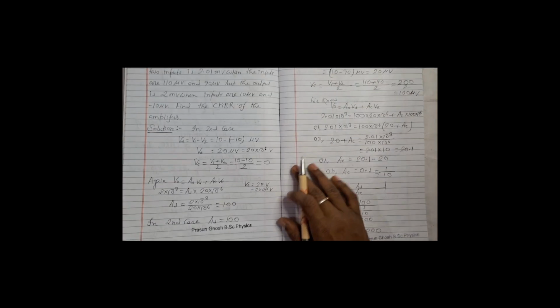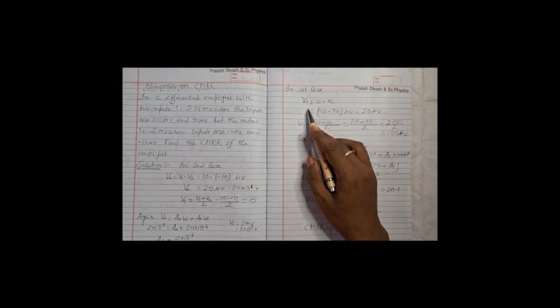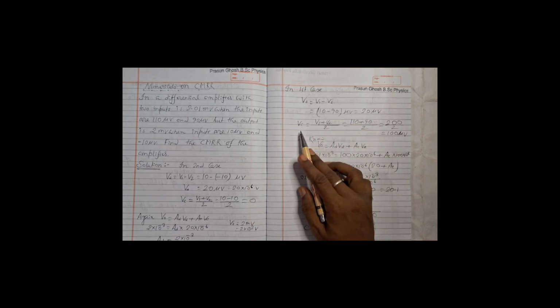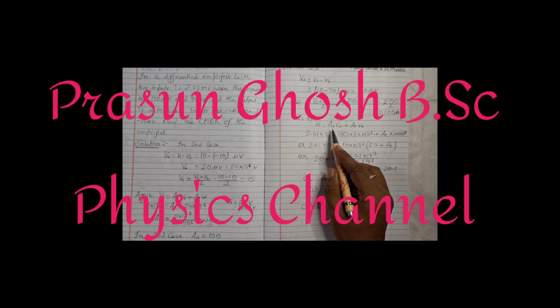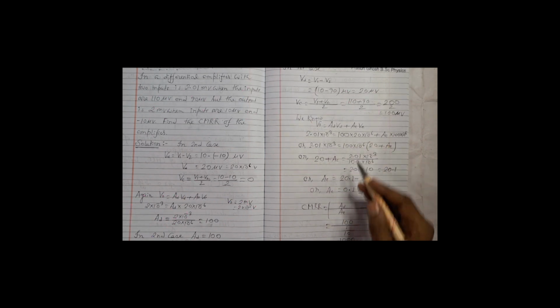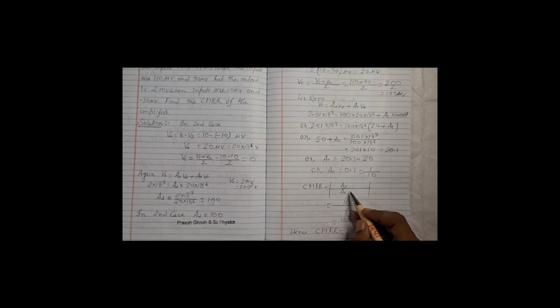Again in the first case, VD is V1 minus V2. So putting the values of V1 and V2, we have to calculate VC. We know that V0 equals AD into VD plus AC into VC. So putting the values we get AC. So CMRR we know is AD by AC. Putting the values of AD and AC, we get CMRR as 1000.